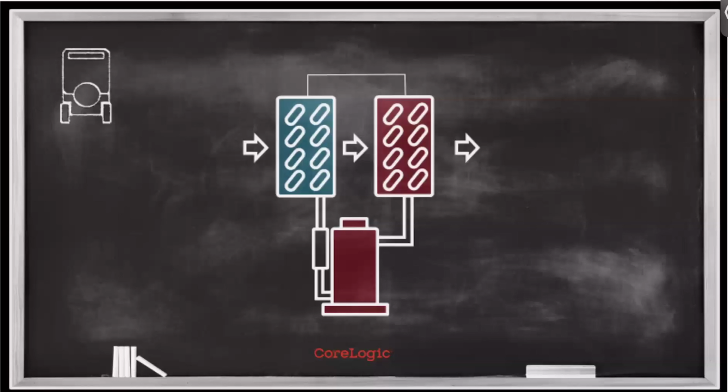All right, so now let's transition more into the equipment specifically and humidity control. The most common type of humidity control system that most restorers are using today is a dehumidifier, and more specifically, a refrigerant dehumidifier. And I want to talk a little bit about the inner workings of a refrigerant dehumidifier for a moment, because if you understand the inner workings, you can leverage more humidity control out of it by really mastering that machine and understanding what it's doing and what its limitations are.